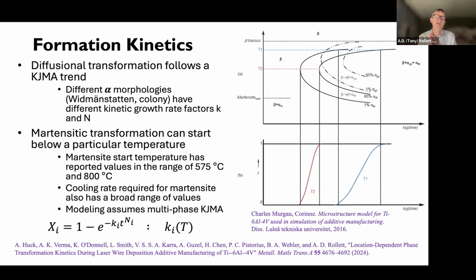And if you get a colony structure with a roughly 1 micron lath spacing, that's very closely analogous to pearlitic structures in steel. And so under optical microscopy, you get this characteristic difference in the appearance. So I'm not going to be able to say anything more about it, but that at least gives you some idea of where that goes.